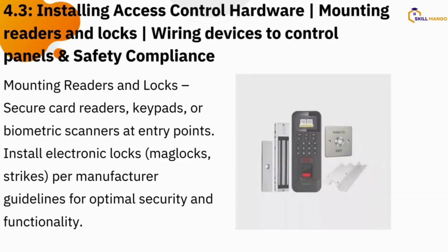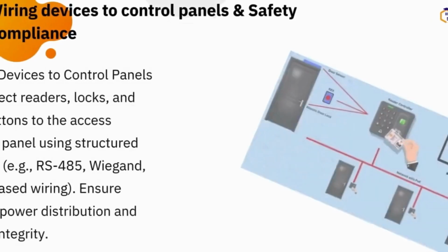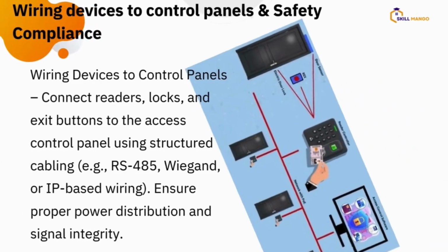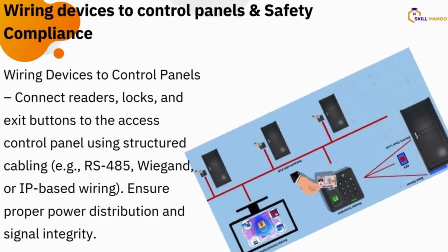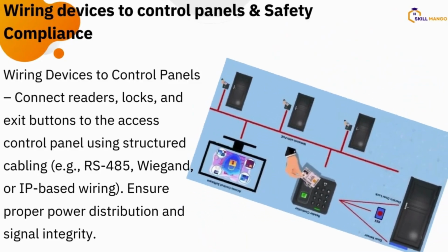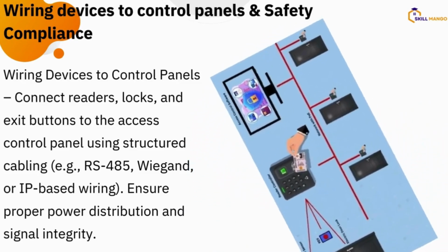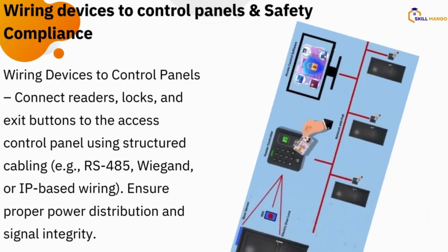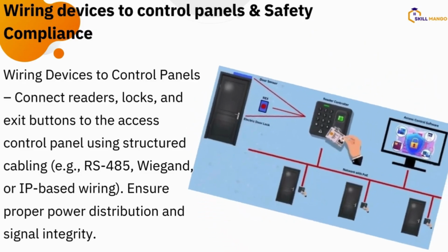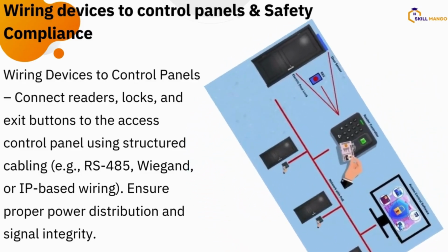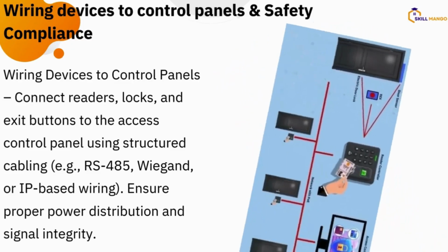All right, so from inside, the other wire goes up to the mag lock. All right, then you position your power supply somewhere to power the device. Okay, so all this has to be well planned and managed. It's very, very important. If you look at this drawing, this diagram, you see that all the wires are meeting the reader. It's very important. All the wires from the mag lock, from the exit button, go to the reader. Then the reader is the one doing the authentication.